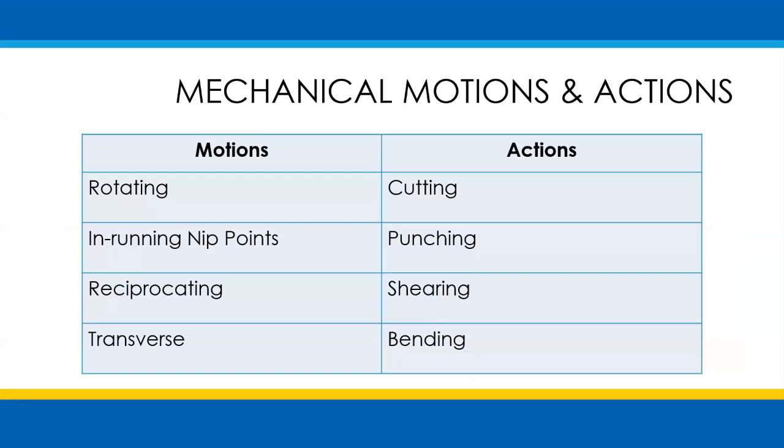The actions or motions that machines perform can present different hazards to workers. A motion is defined as how the machine part is moving, and action is the operation that the machine part is performing. These can include the movement of rotating members, reciprocating arms, moving belts, meshing gears, cutting teeth, and any parts that impact or shear. These different types of hazardous mechanical motions and actions occur in varying combinations in nearly all machines, and recognizing them is the first step toward protecting workers from the danger they present.